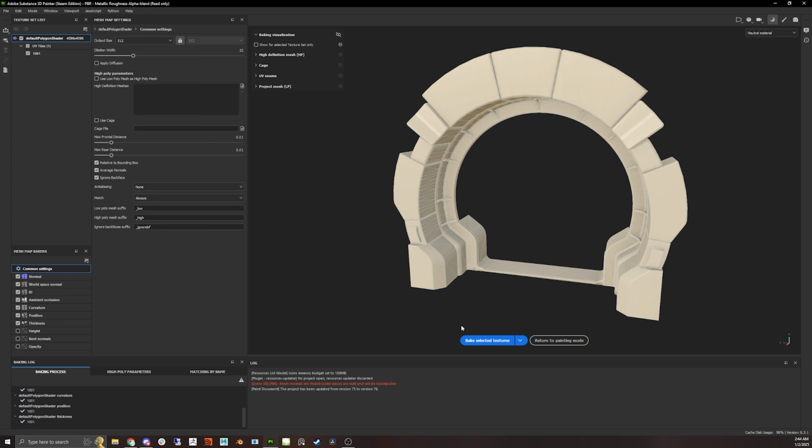The reason why is there's a bug in Substance Painter that if you bake at 512 first and then go to the highest resolution and bake again, it'll be about 3 times as fast. Why? I don't know. It's a thing that's existed since the newest update, I think version 8. I don't know what's going on with it, so I just tell people to get in the practice of doing that.